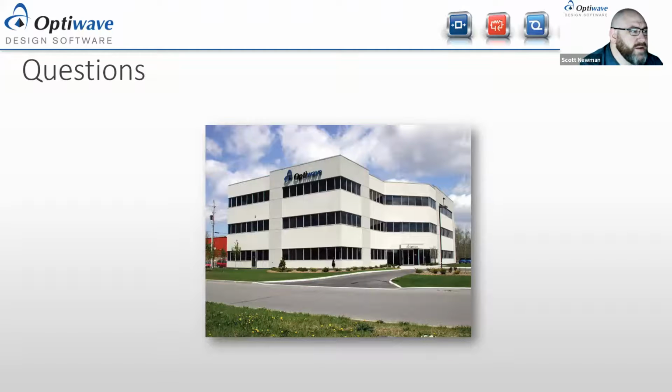I'm just scrolling down here. Yes, sorry. From Gabby, there's a question here about whether you can position the source at different points in the photonic structure. You absolutely can. I wouldn't use a point source in that case. If you were looking at propagation through the structure, I would set up an input plane outside of the domain and run it. But yeah, you can put the source wherever you want. It just depends on what information you're looking to get out of there.